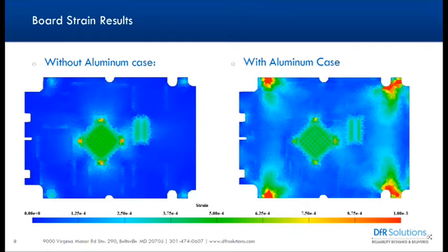Now, if you're doing this in Abaqus or ANSYS or any other one, what you're trying to do is a static structural analysis where you apply a base temperature and you go up to the highest temperature. In this case, it would be the highest temperature in your test. You can also do an environmental test, which would be environmental modeling, with the highest temperature in your environment.